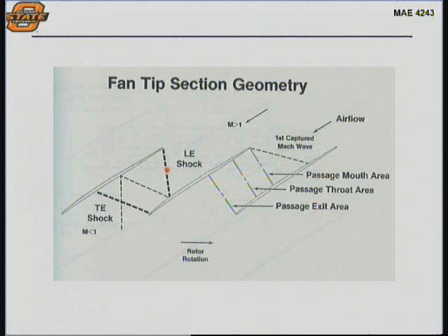characteristic sound. In fact, a lot of the modern fans have swept leading edges, for the same reason you have sweep on the leading edges of supersonic fixed-wing aircraft. It's to delay this compressibility. It's to make these shocks weaker. Early on, they didn't do that as much. In fact, because they couldn't manufacture the curvature that they can now with some fancy composites, some of the early large turbofans, because they had large diameters, had Mach numbers that were like 1.4.